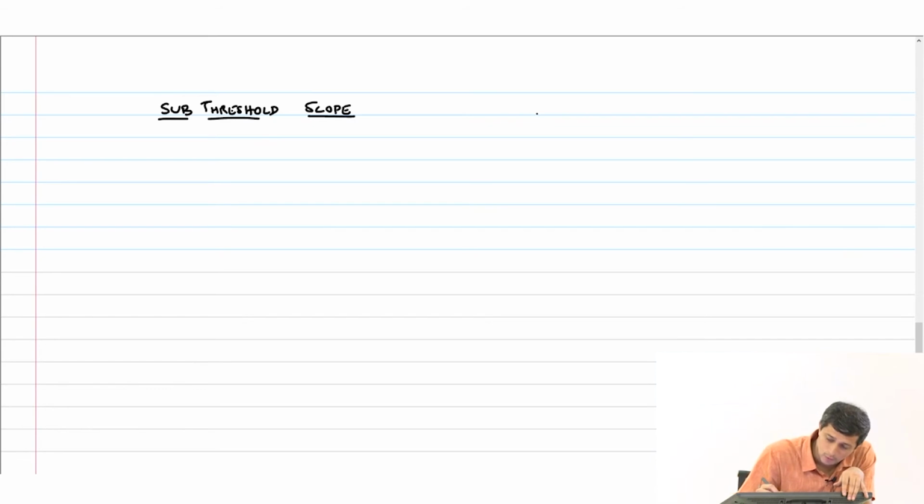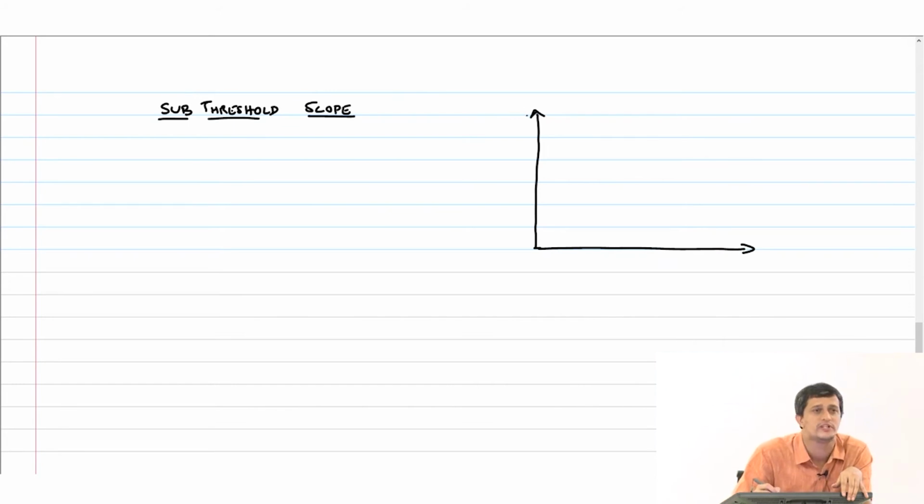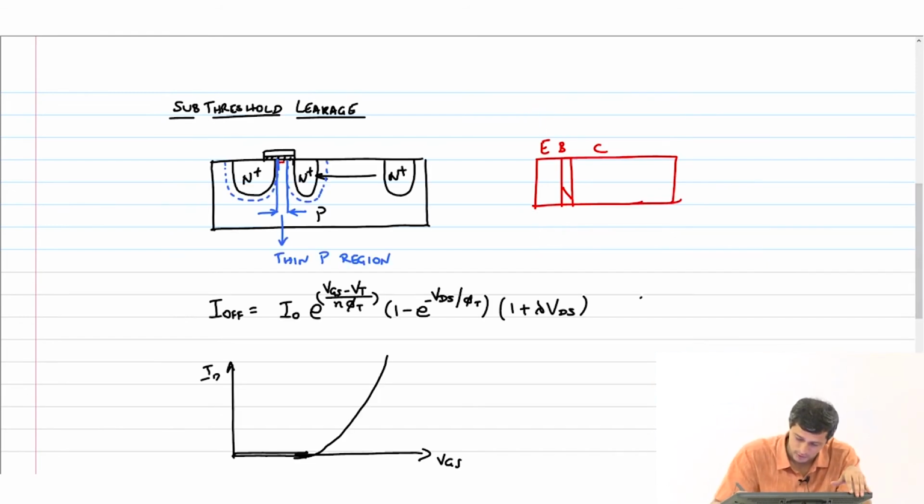So first of all, if I want to look at the effect of subthreshold current, right, I can now not plot ID versus VGS, because the magnitude of the current is going to be in nanoamperes. Okay, this subthreshold equation that we wrote typically will be somewhere in nanoamps.